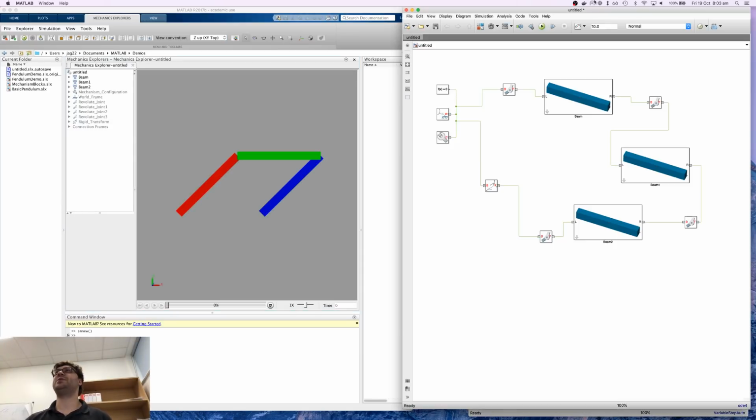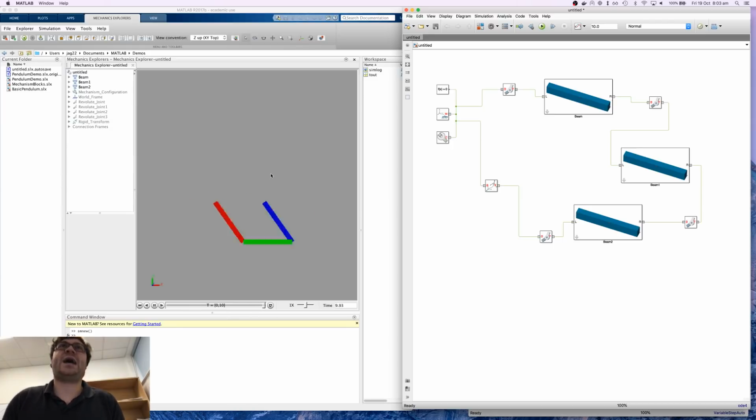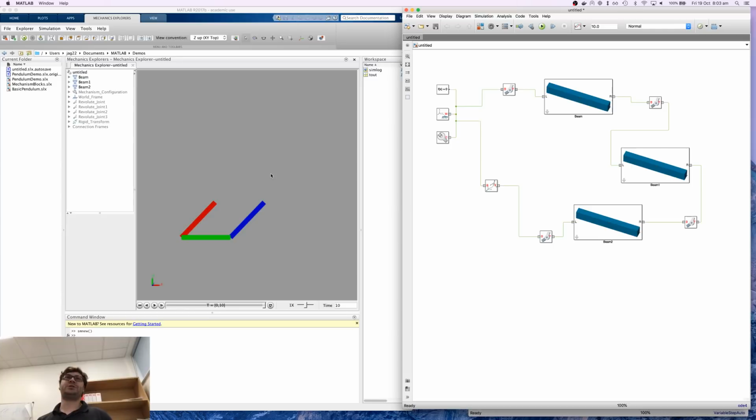We should be able to simulate this now, and what we'll see is it just swinging due to gravity. And there we have it. That's our simple mechanism, all jointed up, and it's just swinging against gravity. So now we want to understand how we can work out what torque we require just to keep it in that position. If you're looking at your car convertible roof, that'll be the torque it would need to overcome to start actually deploying, or to retract.